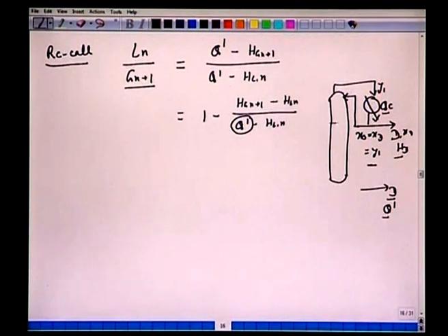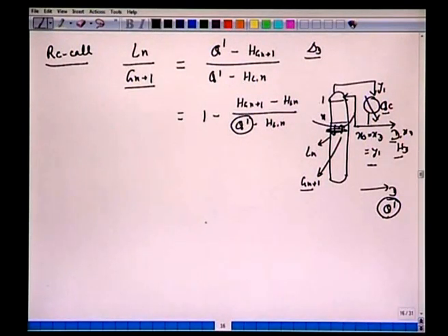We said that if we choose any plate here, n, then Ln, and we have this Gn plus 1. The difference between the two molar flow rates is the same as D, and the difference between the energy of the two streams Ln and Gn plus 1 remains the same as Q dash. So we had this differential point given as delta T. All right. So this is true with any envelope which we choose around the plate number n counting from the top. So we came to these expressions and we can write like this.